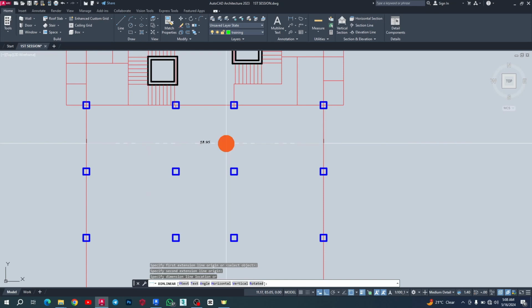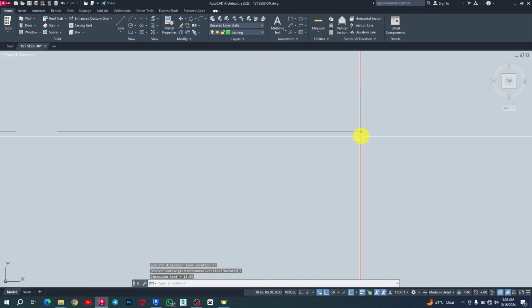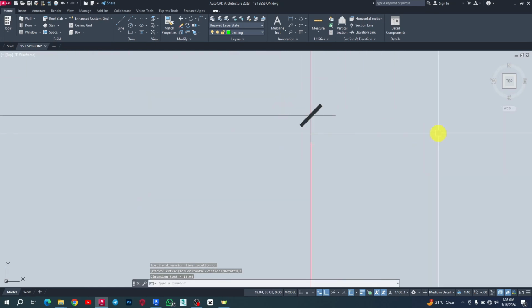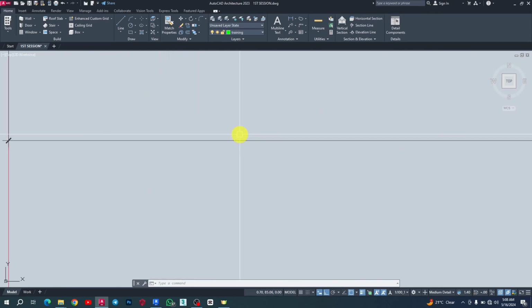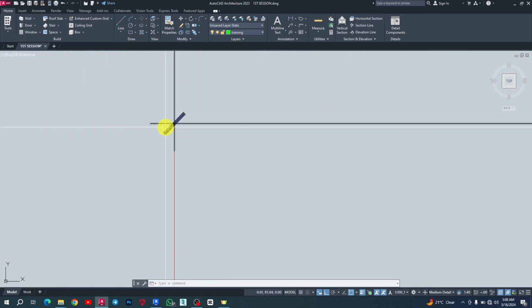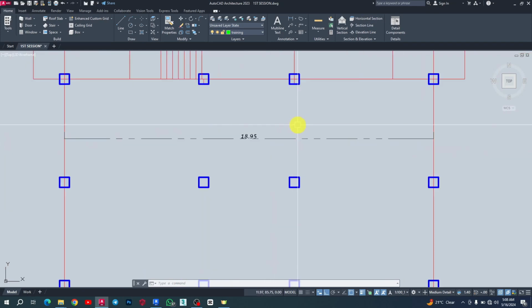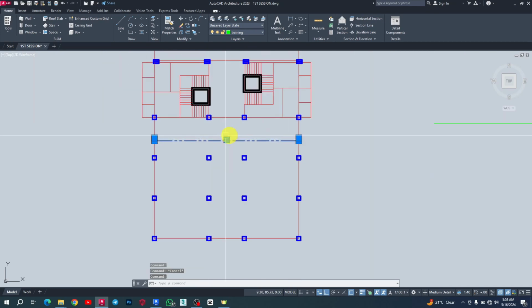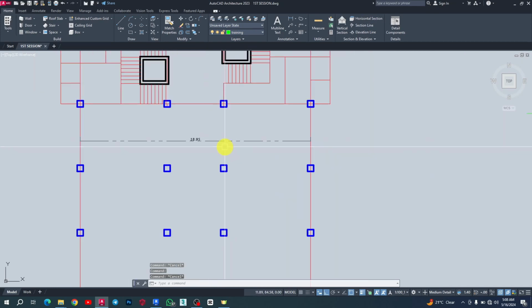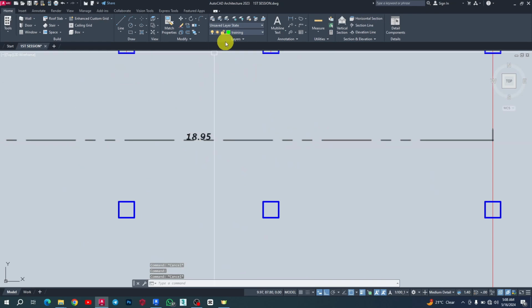So when you look at my dimension style here, you see the arrow size is very small, it's slanted, architectural tick, so it's slanted, and then the size of it. And then since I use everything by layer, when I draw on a particular layer, it's going to follow that layer that is currently active, right? So my layer here is dash line, and you might be wondering why it is dark when the line color is green.